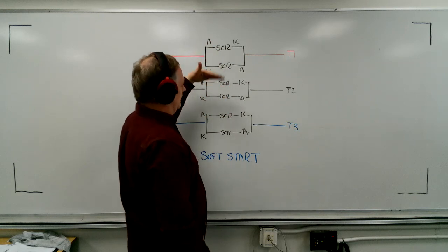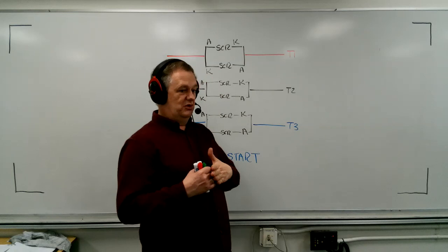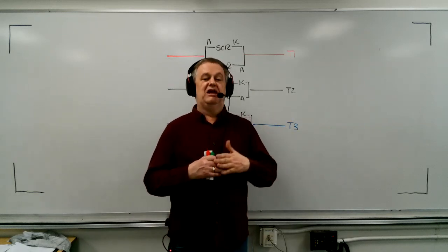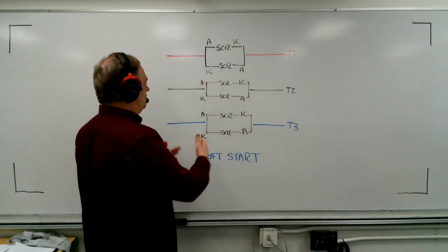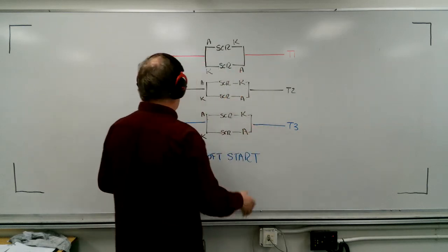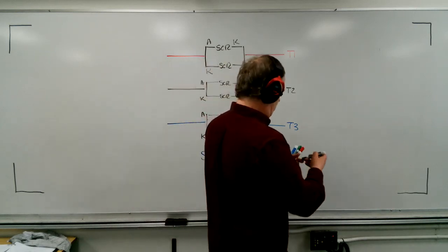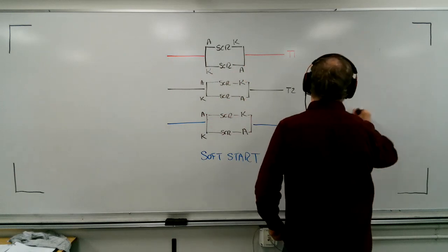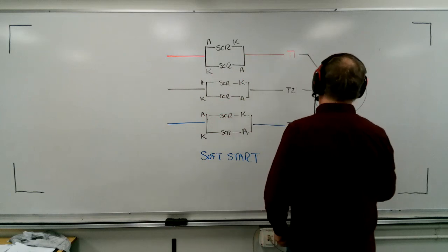So you're going to get your perfect three phases apart, but the voltage per phase will rise and fall depending on where your firing angle is. And so you can smoothly vary your output voltage of the soft start anywhere from 0 to 100% voltage. And that, of course, will be a very, very smooth way of starting this three-phase motor.